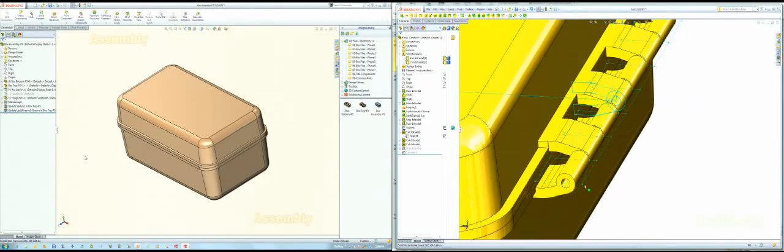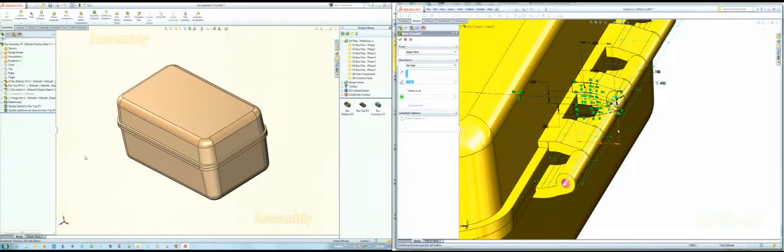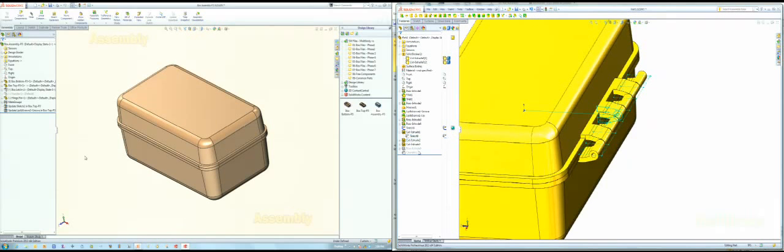So that got us to this point, and then I actually extruded another feature, both directions, mid-plane, but I did not merge it with anything else. So now we're going to have 3 bodies. We're going to have the top, the bottom, and the hinge pin. And they're not merged, and then I just added a chamfer on the end so you could tell it was a pin. So now we've got 3 bodies in our part, okay?